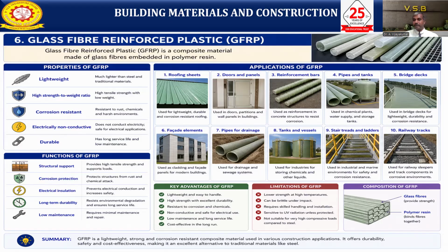We use it in bridge decks because it is lightweight, durable, and corrosion resistant. Nowadays we are using GFRP materials for facade elements, cladding, or the appearance of panels in modern buildings, and GFRP materials can be used for drainage purposes.